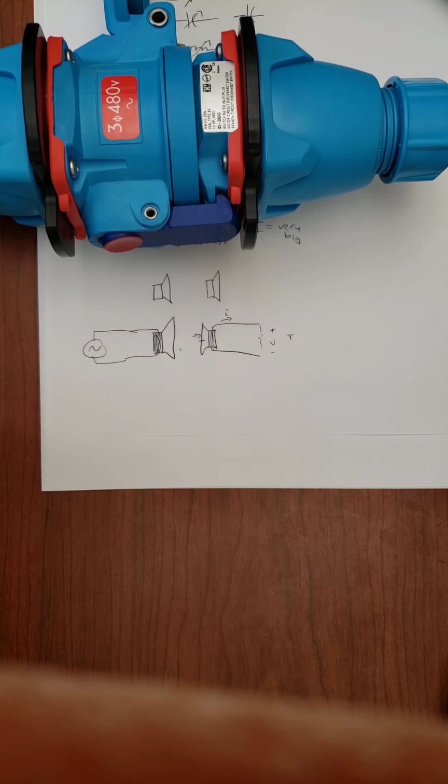In an industrial setting with higher voltage, you may not do that. You may not just walk over to the box. You may have a tool that you stand a long ways away, like a big fiberglass broomstick, that you poke it with, because of this arc flash.